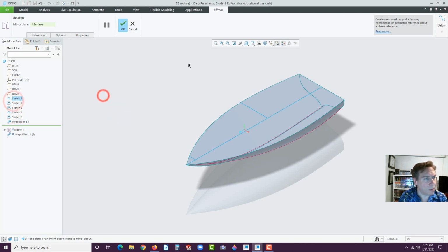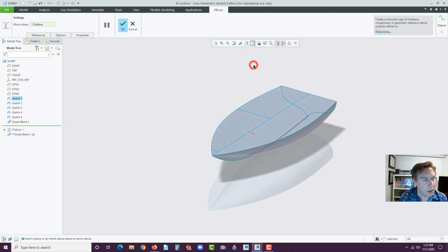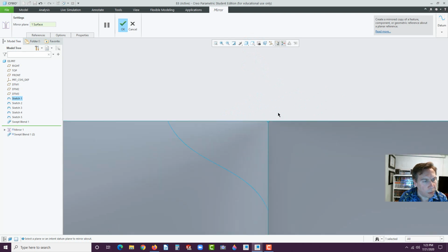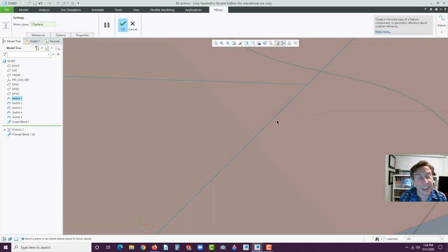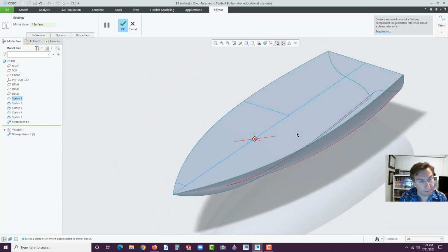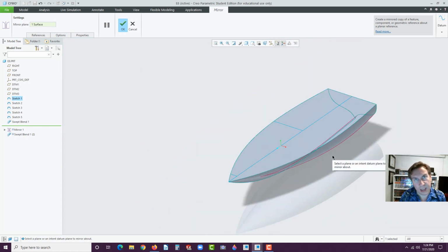Or you could actually look at them from the front view orientation. Here's probably the best way. You go to front, and then you zoom up really close like this. And see this thin blue line? You'll usually see a double blue line. You find that blue line, which sketch it's on, and edit that sketch and fix it. Just have to move it over to align with the others. Use a coincident relationship or set it to 0 for that dimension.